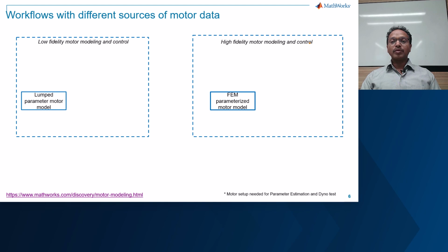Lumped parameters would simplify the model and give the advantage of faster simulation. But what if you want your model to behave closer to your actual motor? Then an FEA-based PMSM model would be a better choice. This is because instead of having constant parameters for inductances and permanent magnet flux linkage, now your motor has a nonlinear mapping between flux linkage, current and torque. So this will give you a realistic closed loop simulation.